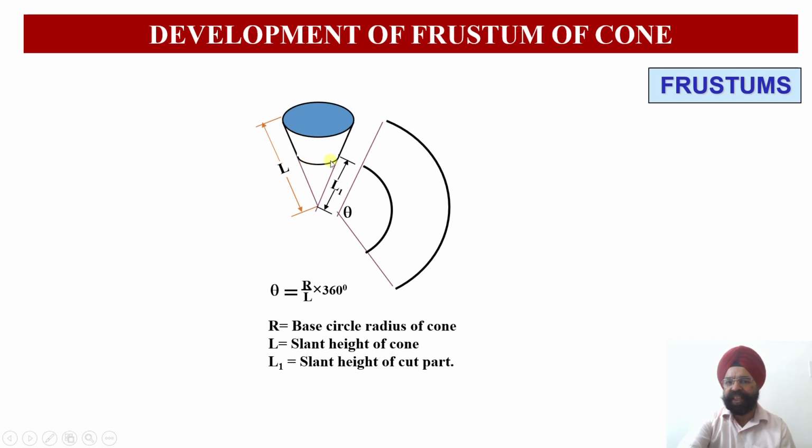And once I divide this smaller circle into 12 equal parts, I will be measuring the length of one sector, and in the same way this will be 1, 2, 3, 4, 5, 6, 7, 8, 9, 10, 11, 12 and 1. So all these points I am going to mark corresponding to the sectors of the smaller circle, and then I am going to join this dark, because this portion has been removed, so I will be joining this portion dark.